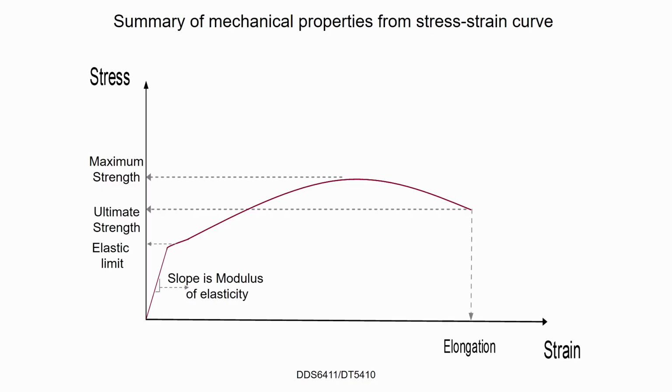But the stress strain curve is constructed by using the original dimension. If you replot this using the current cross-sectional area, you will see that the curve continues to increase. So you're right. The ultimate strength, if you determine it that way, will be higher than the maximum strength at this point. Well, at least I get a laugh from you, necking.